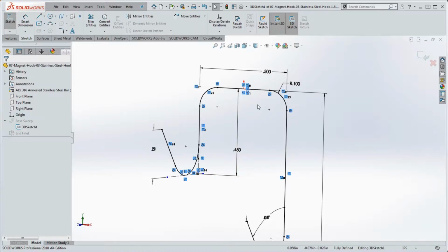And as you know, when you're in a 2D sketch, you have a choice between horizontal and vertical. The difference between that and 3D sketching is that in a 2D sketching environment, you only have horizontal and vertical, and that's usually determined by the orientation when you begin to start sketching your model out. If you think about the top plane, if you're sketching something out, there really is no vertical in the top plane. But it's how it's oriented on the screen when you begin to sketch that makes that determination.